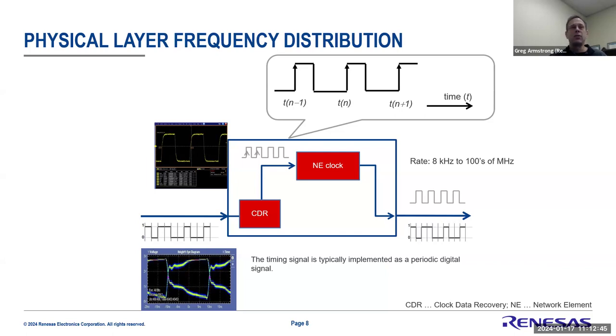a signal. And so in synchronous networks like SONET and SDH, that would aid in part of the synchronization protocol itself. For Ethernet, the synchronization of the physical layer isn't as important. And so a lot of times there was no real relationship between the recovered clock and the retransmitting clock. The transmitter usually just used its local clock to clock the data in, and it would re-clock the data out with its local clock.